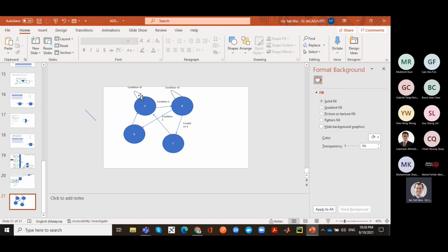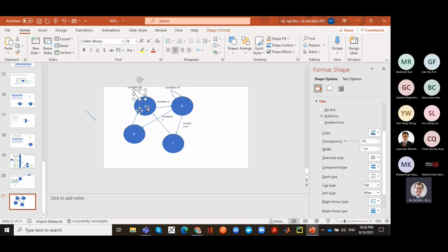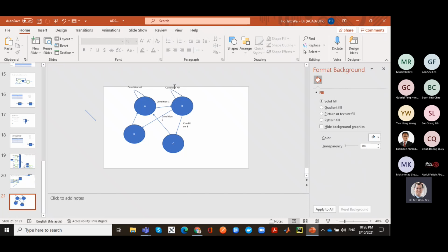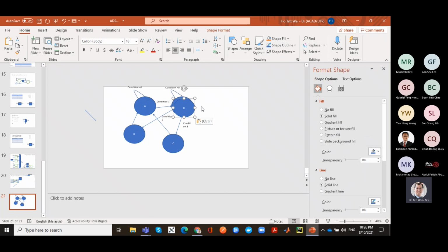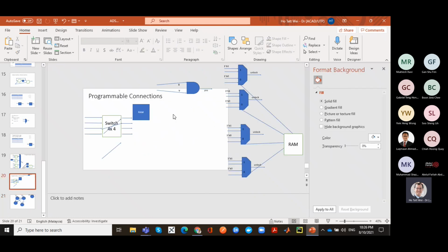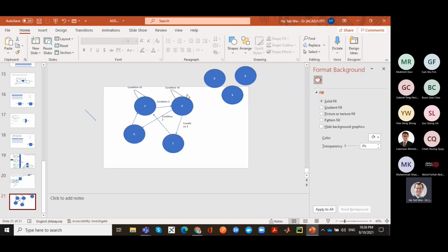Okay, in general they stay in that mode or they stay in that state until the computation is done, and that is actually signaled by some kind of condition signal. So you will transition to a different mode, a different state when that condition is done. Okay, and in order to calculate this condition, you can actually have another state machine that is calculating this condition.